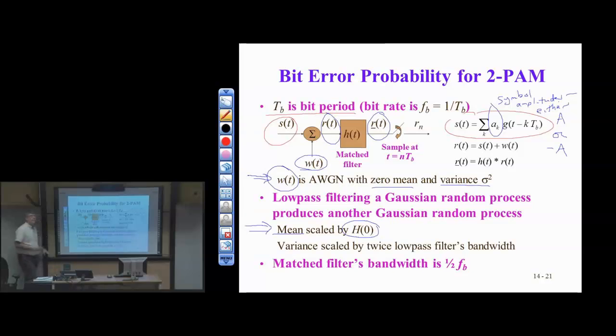And it's more like this Gaussian distribution exists for all time steps. Correct. And the Fourier transform of this signal does not exist. Yeah, that's the problem. But the power spectrum does. So if we were to observe W of t for all time from minus infinity to infinity, this is theory, then the power spectrum is flat and the value is sigma squared.